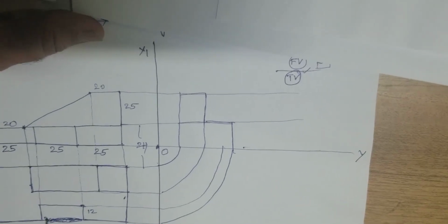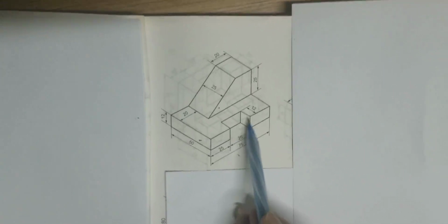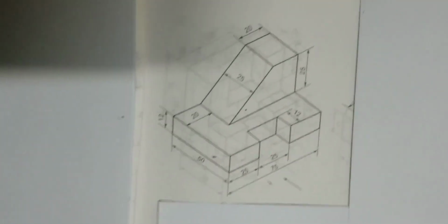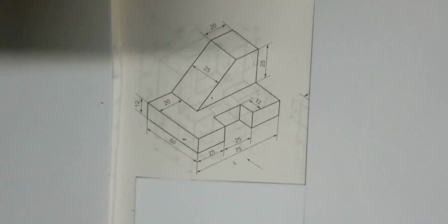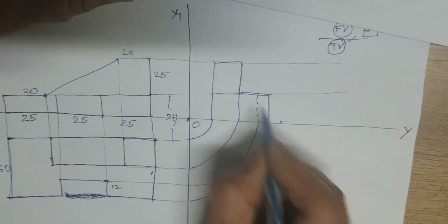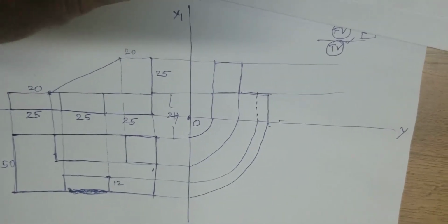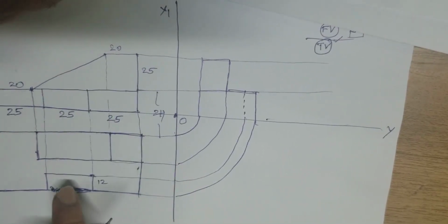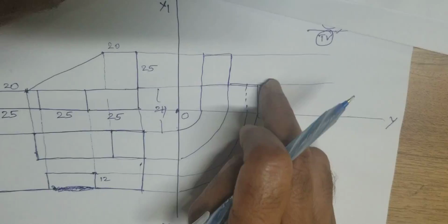Then what about this cutting portion? This cutting portion, when you are seeing this side, we know there is a cutting here, but it is not seen when you are seeing it, because this is there inside. How you have to mark is that this side, see here, this portion we have to make the hidden line. This is enough when we are having full question. So this represents front view, this represents top view, this represents side view.